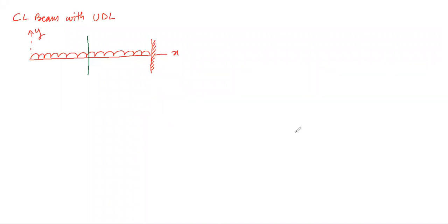This case is cantilever beam with a UDL, right? So based on this, let's define, suppose W kilonewton per meter load is acting at this particular point, and this is at X distance. So we all know that it is a UDL, so its line of application is also defined at X by 2. The total load at X section is defined as WX. Therefore, the moment Mx in this case is defined as minus Wx square by 2, right?